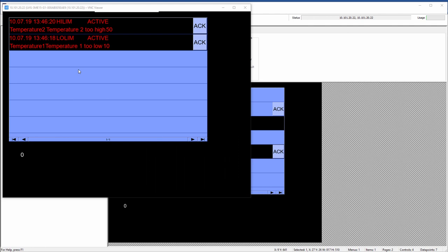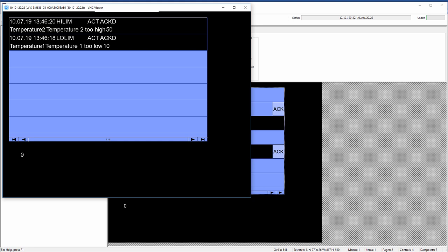Alarm list controls provide new colors for active acknowledged alarms and alarms that are no longer active but pending acknowledgement. If multiple alarm server data points are connected to the control, it is possible to set a filter during runtime to only show entries from a certain alarm server.